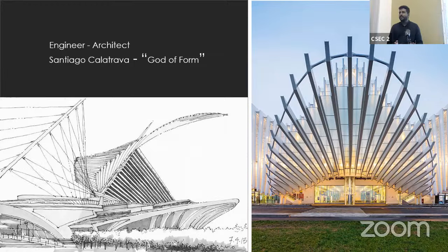A 225 column is like a general thing. Okay, let's make it 150 by 400. Okay, let's remove a column and put a 150 concrete pier wall in that particular space and get that clear space. Very small design, but it has a huge impact on the spatial quality of that space. Just imagine we have two huge beams crossing over this soffit in this boardroom, from this end to that end. We have a beam right here and a beam right there. Gone. Those are very small things, but they have a huge impact on the design.